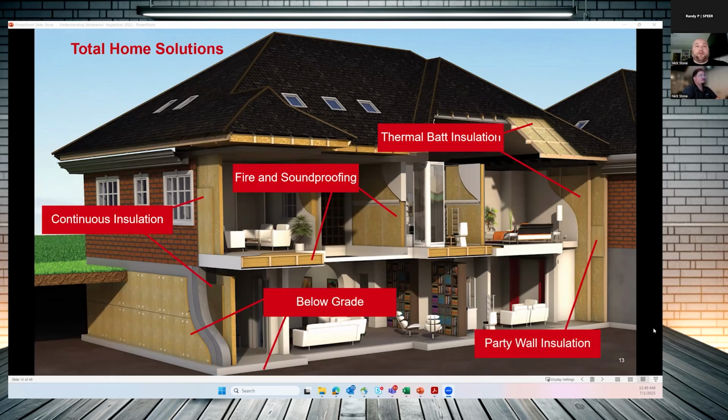or 6-inch product. So 3-inch for your interior walls, 6-inch for your floor assemblies. This is going to be offered in 16 or 24 inches on center. We move to our Comfort Bat, which is our exterior wall. That's offered in a 2x4, 2x6, 2x8, and 2x10. For the 2x4, we have an R13 and an R15. For 2x6, we have an R21 and an R23. For a 2x8, which is really moving into your roof assemblies or overhang areas and things like that, that's going to move into your R30. And then your 2x10, now you're offering an R38.